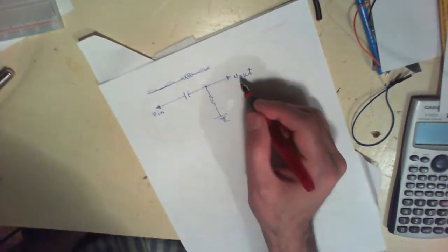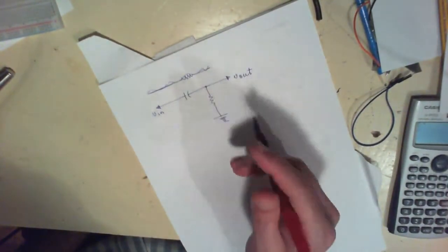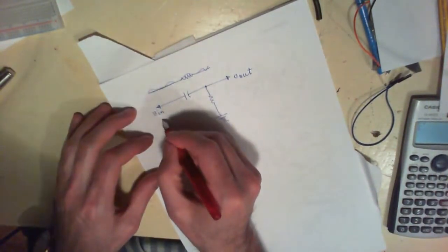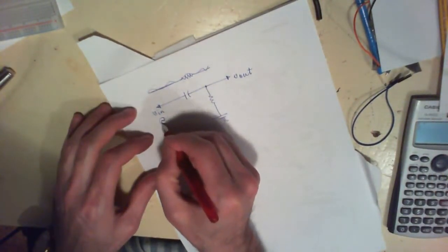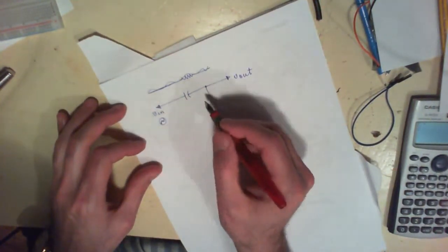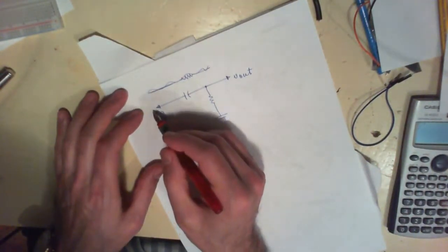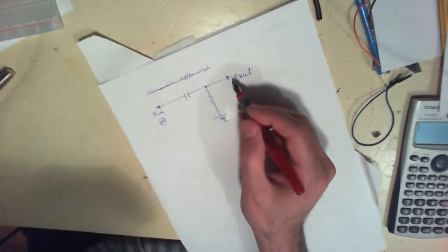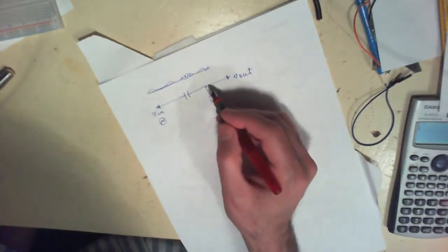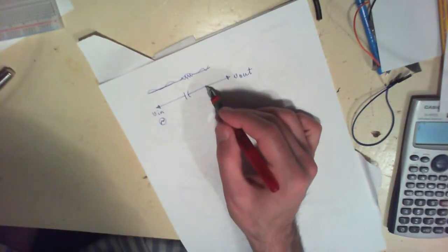And then you use this in an AC circuit, as some sort of voltage divider or a filter. What that means is that here you will usually have a signal generator or some sort of sine wave signal going in, so this is an AC signal going in, and usually, based on the frequency of this signal, you will have some sort of voltage over here.